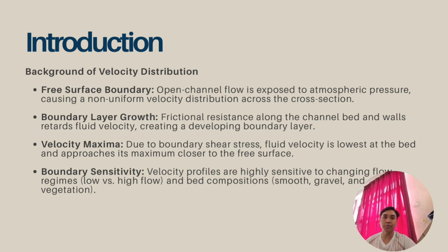Velocity maxima: due to the boundary shear stress, fluid velocity is the lowest at the bed and approaches maximum closer to the free surface. Boundary sensitivity: velocity profiles are highly sensitive to changing flow regimes and the bed composition, which is smooth, gravel and vegetation.